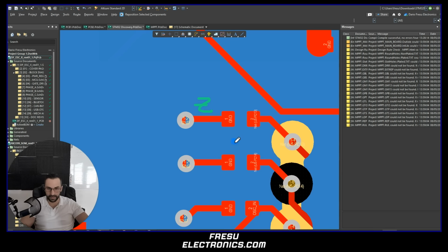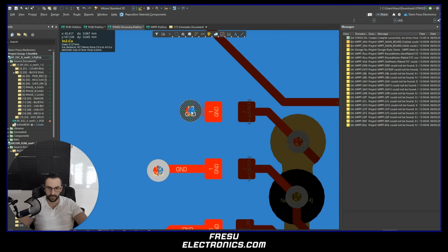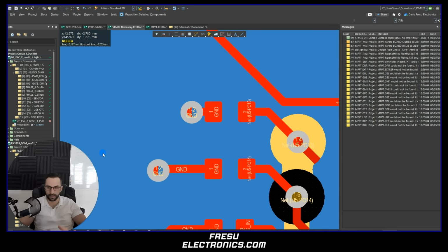And then if we have an impedance here, and we have a current which is flowing through this impedance, what we're going to have is a voltage. And this voltage here is noise. So depending on how sensitive your system is, this is going to create some issues. So this type of connection, we want to keep as short as we can. In certain cases, we can also use vias in pad, but this, of course, is going to cost us some extra money. But anyways, in most boards, you can just route this as close as possible, and you're going to be just fine.